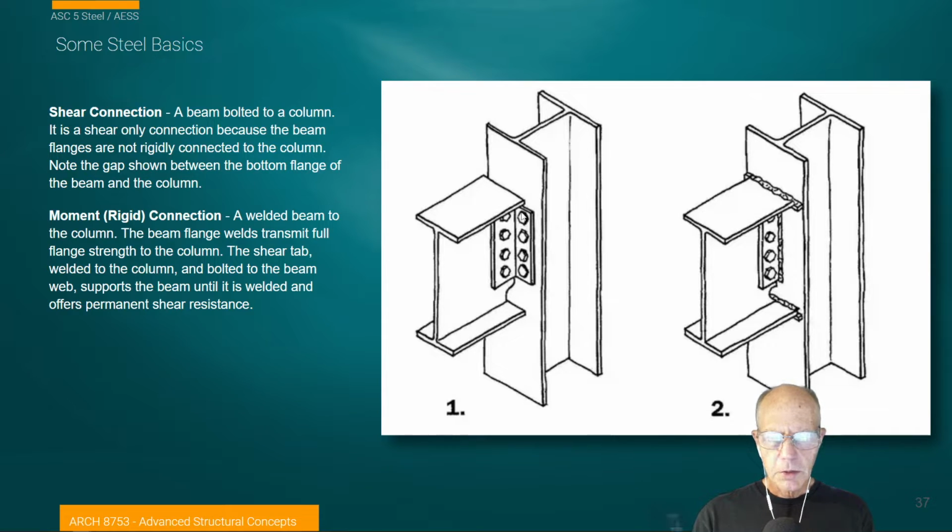We made specific efforts in the construction of the way we've cut this beam to make sure that we're not going to transfer any moment. So actually, if you look at this bottom, you can't see on the top flange, but if you look at the bottom flange, there's this cutaway section, and the flange comes up short of the actual column that has supported it. And that's so during deflection, none of the moment energy, that twisting moment energy, is delivered into the column assembly. But we can, in many cases, decide that we want that moment connection, that rigid frame.